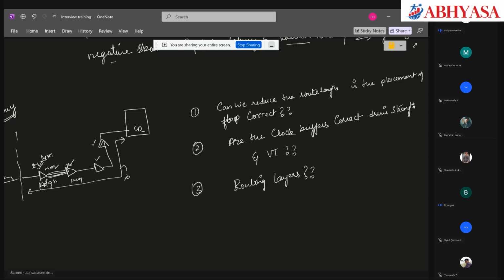So why are we using 4, 5, 6? Because other layers are not free. Those layers will support routing. Understood. That's the answer. So top layers are used for power.